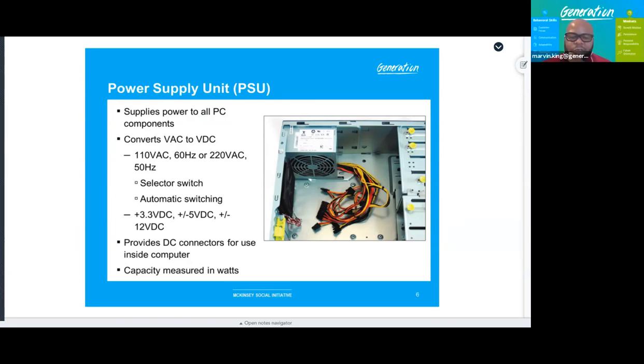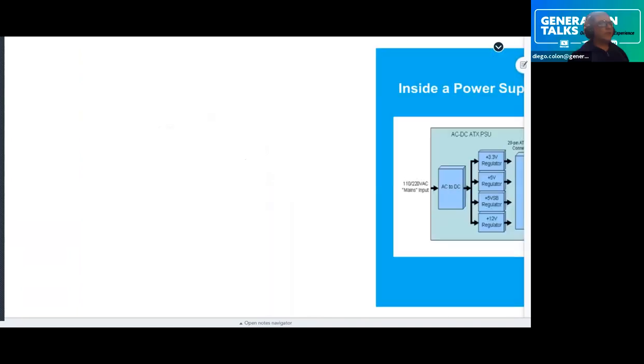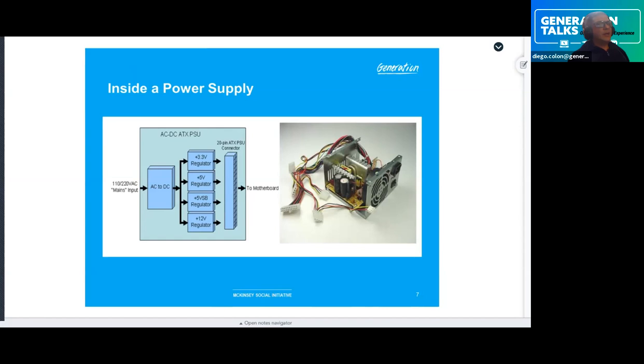Test question. They will ask about those particular high-low power numbers there. And they'll also ask you in reference to these devices. As for the actual P1 here, you'll notice that when it comes from AC to DC, the 20-pin connector itself brings in the 12, you have the 5, you have also a 5 here and another 3 area. We'll see the details of each one.